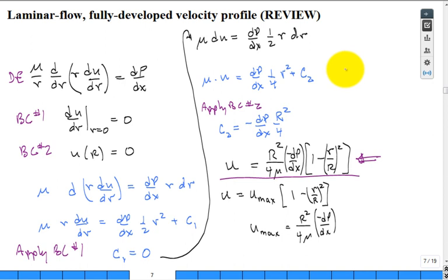So if I go back and I say, here is my center line, and I'm going to measure r going out from 0 to cap R, the velocity profile is flat right there, and it goes to 0, no slip, and that's my velocity profile as a function of r, and it's quadratic in terms of r, isn't it? Sure, it's a quadratic profile. So how did you get that in fluid mechanics?